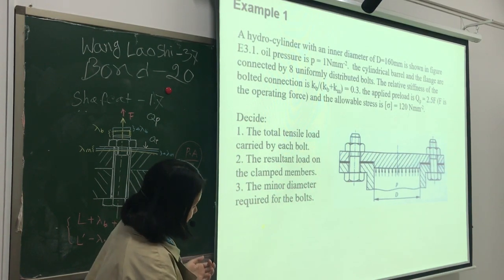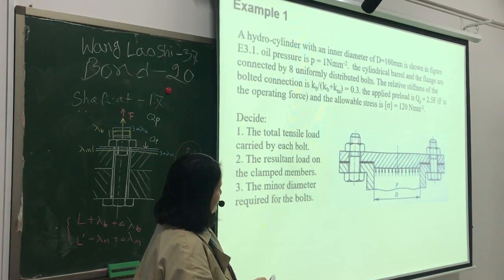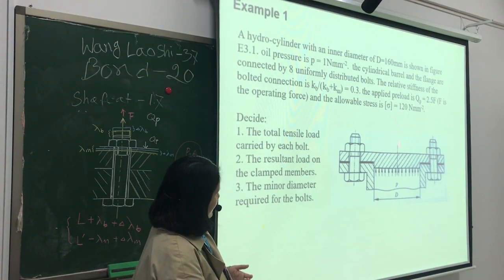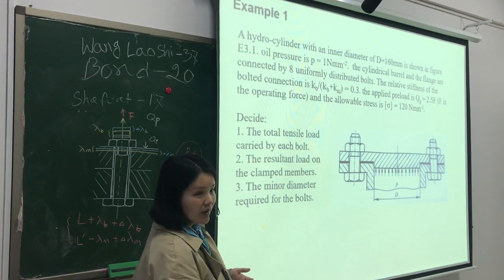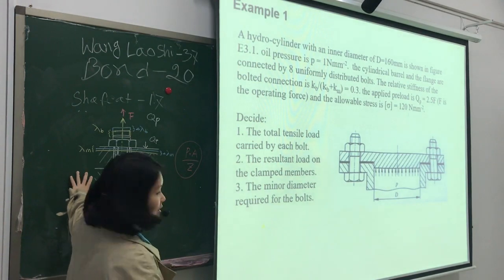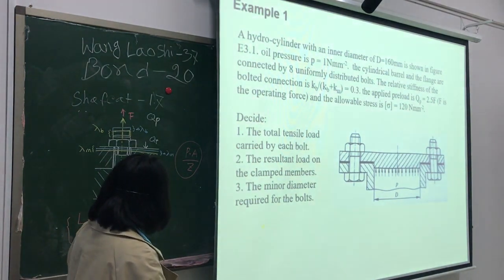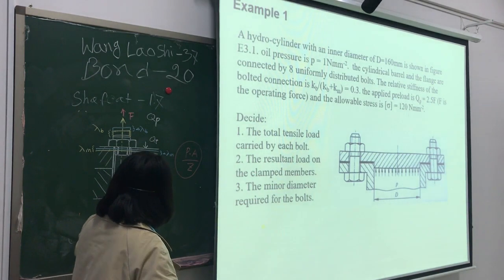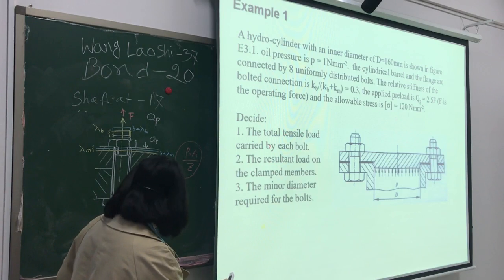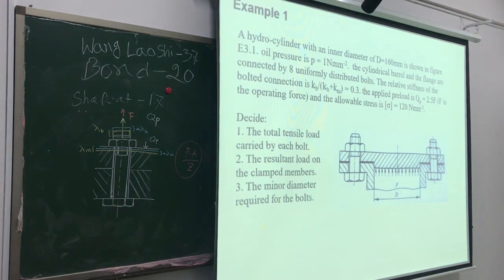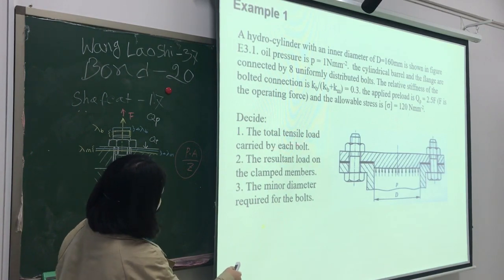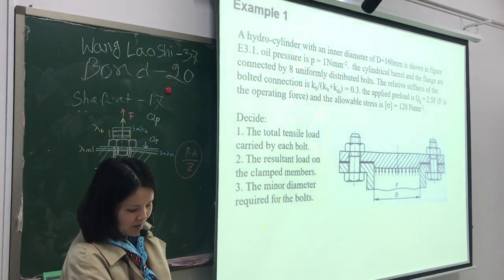This is the condition of the combination of a preload and an axial force. Under this condition, first we calculate the total tensile load carried by each bolt.